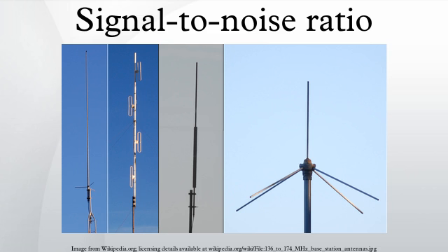Optical SNR. Optical signals have a carrier frequency that is much higher than the modulation frequency. This way the noise covers a bandwidth that is much wider than the signal itself. The resulting signal influence relies mainly on the filtering of the noise. To describe the signal quality without taking the receiver into account, the optical SNR is used. The OSNR is the ratio between the signal power and the noise power in a given bandwidth. Most commonly a reference bandwidth of 0.1 nm is used.